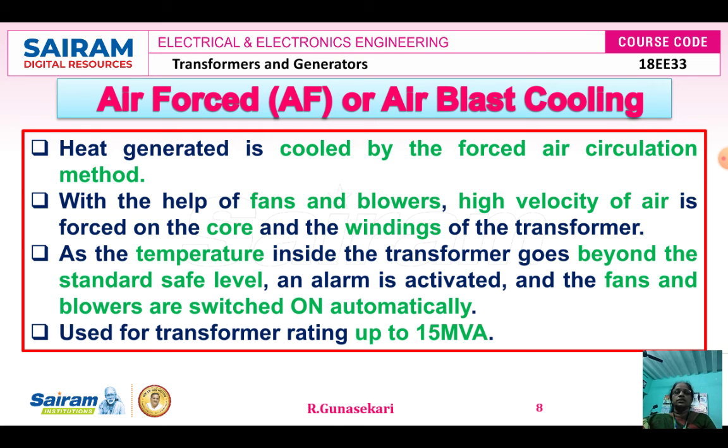If the temperature inside the transformer goes beyond the standard safe level, the alarm is activated and the fans and blowers are switched on automatically. This is the main key point of this type of cooling.